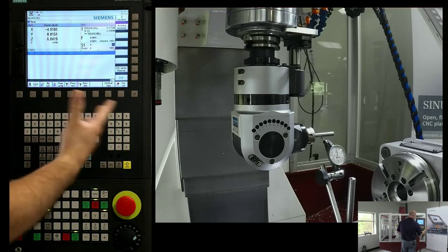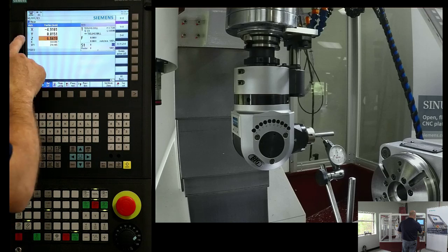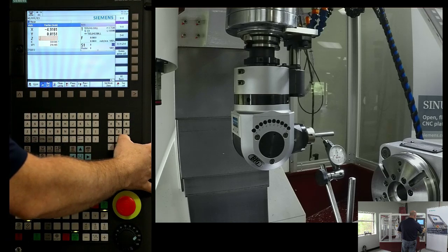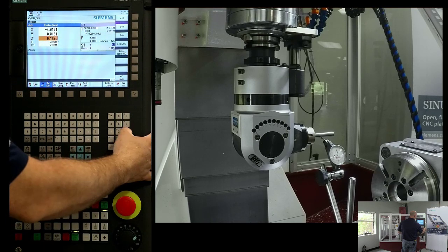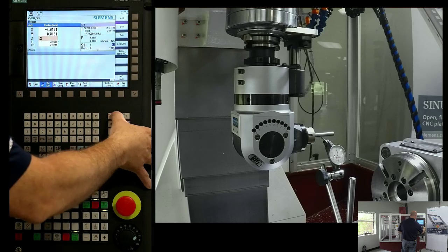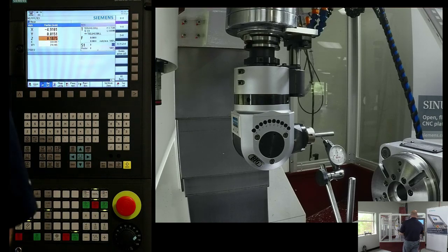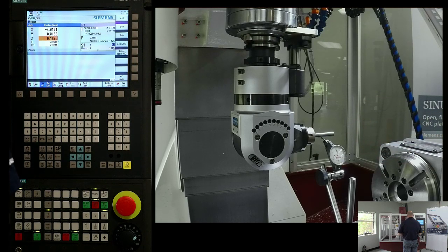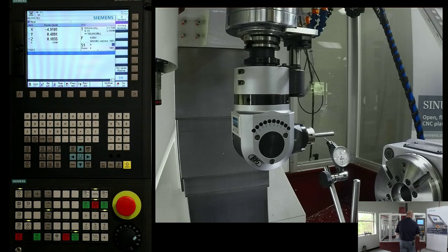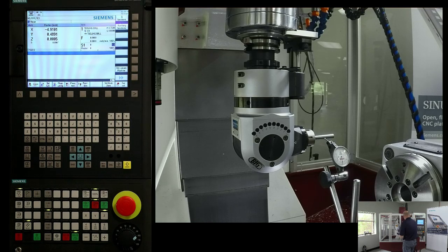So load up a work offset, something that you don't mind rewriting or overwriting. Go to our set work offset and set the Z-axis to be half of whatever your standard is. So .1875. And if we did the math, I can show you that, 0.375 divided by 2, right? There's your .1875. And this is in a plus value. Because what I'm saying is, if I was to move the machine, all right, so we can do it right now, if I was to move the machine down to 0, when I get to 0, I'm sitting at the center line of this axis. And this is our first step.